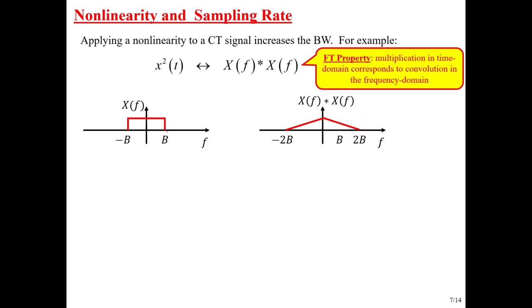So if this one was sampled, let's just say we're sampling so that fs over 2 is just a little bit bigger than b. Well, now our fs over 2 for the squared one is there, and that means that this tail is going to flop back in because this thing is going to get moved out to be centered at fs. And there is aliasing that happens.